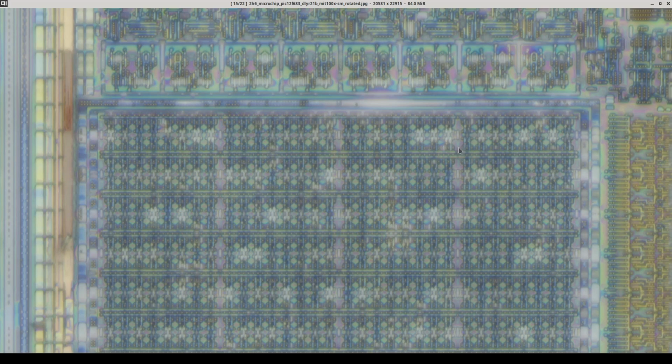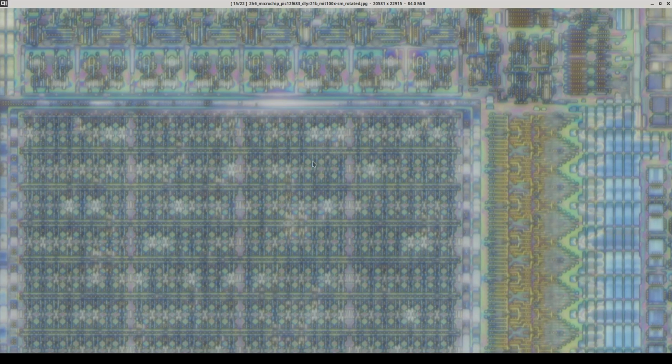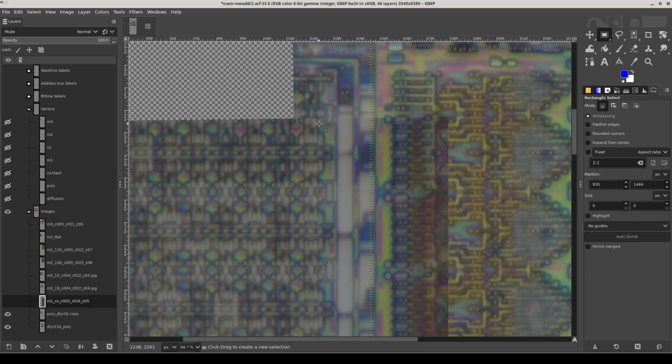And so if we look more closely, we can see there's actually a contact every 8 bit cells that goes up through the entire metal stack, all the way up through metal 1, metal 2, and finally up to metal 3, and then ties onto this parallel word line, which is just there to provide a quick low resistance connection down to here. So rather than having huge voltage drop in the poly word line, we have a very low voltage drop here, and then the current is able to go down to the poly and drive it from all ends at once.